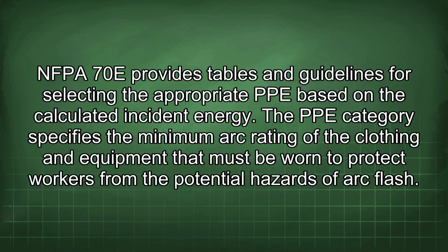NFPA 70E provides tables and guidelines for selecting the appropriate PPE based on the calculated incident energy. The PPE category specifies the minimum arc rating of the clothing and equipment that must be worn to protect workers from the potential hazards of arc flash.